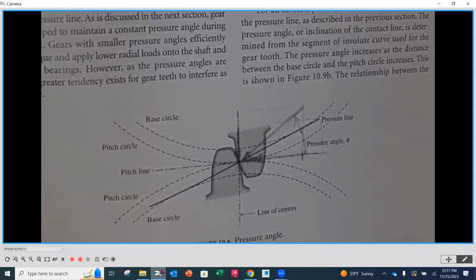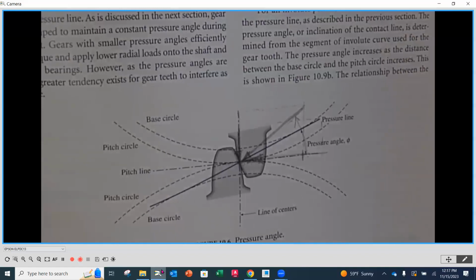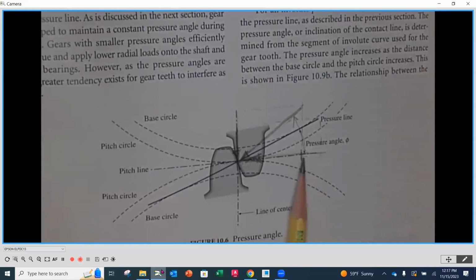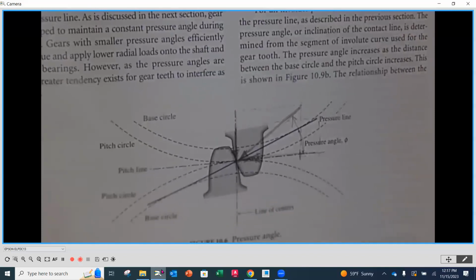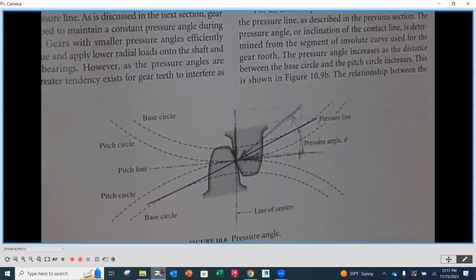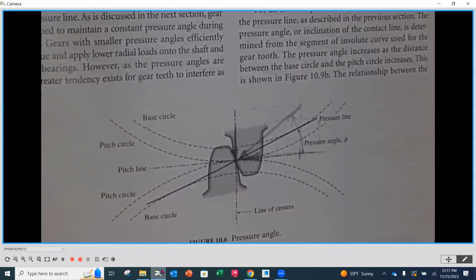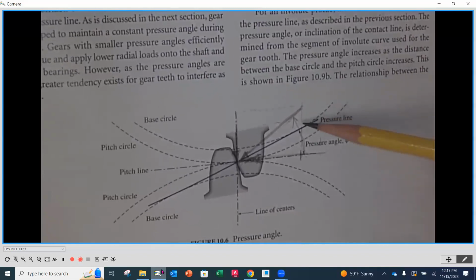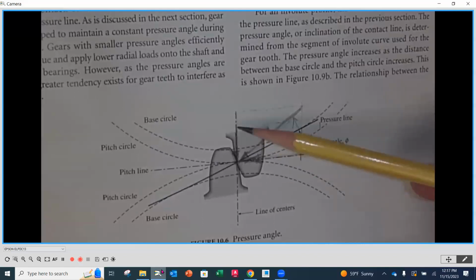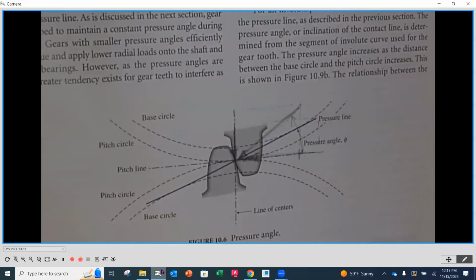That's an application where we want at least a 25-degree pressure angle, because we want to minimize pushing that tooth over or shearing it off. But with smaller applications, like our regular industrial-strength ones with middle-of-the-road torques and horsepowers, going with 20 lengthens this out a little bit, and we have minimal radials going down through there.